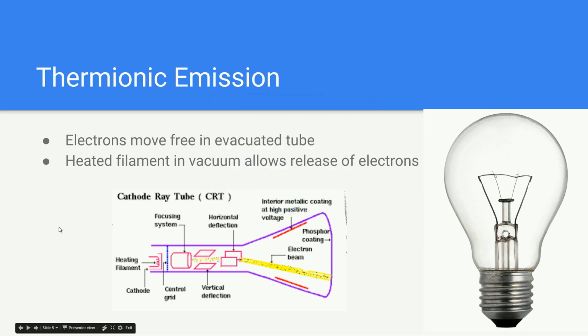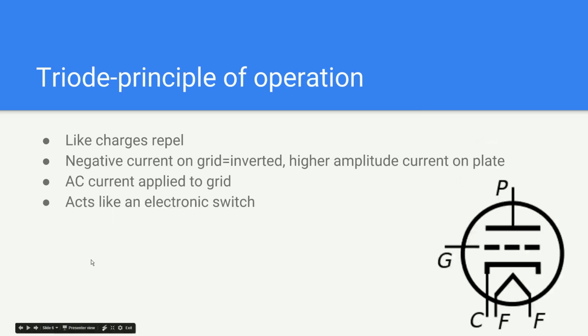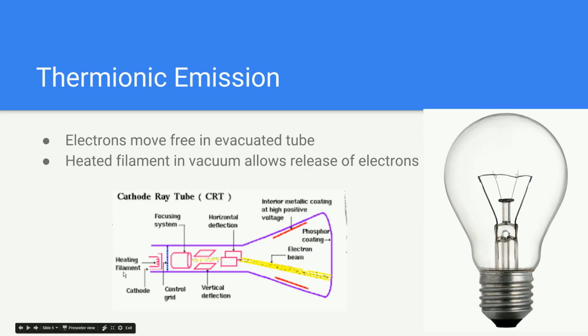In an old tube TV, they call them tube because it uses a cathode ray tube. It's basically like a really fancy vacuum tube. In the back you have this filament that heats up the cathode. The cathode then, as I read in a book once, quote-unquote, boils off the electrons. You have your grid here to control your brightness in, say, a black and white TV. It focuses those electrons into a beam, deflects the electrons vertically, and then deflects them horizontally, so that you have a single beam which can be drawn anywhere on the surface of the screen.